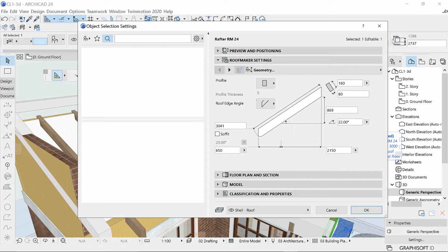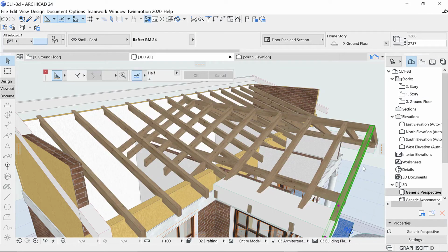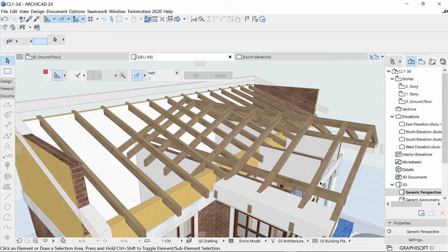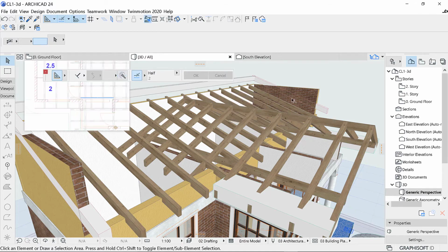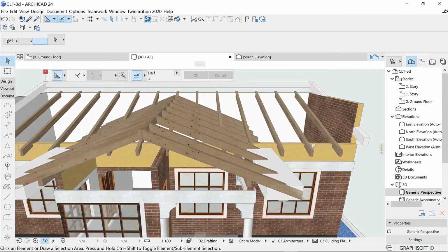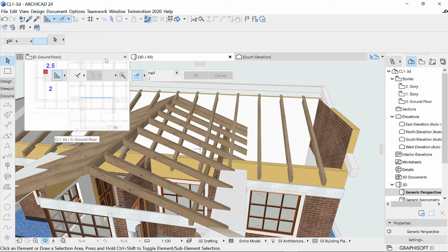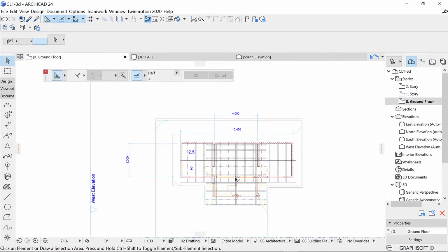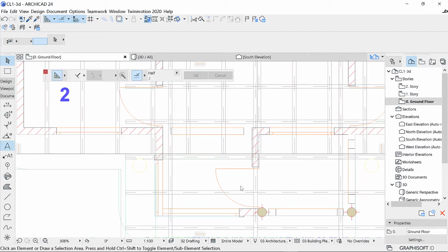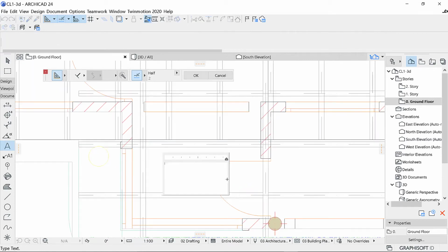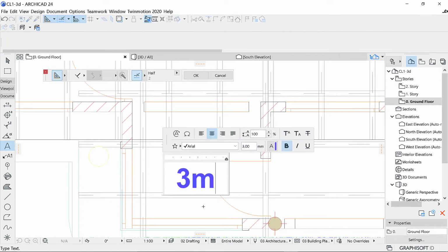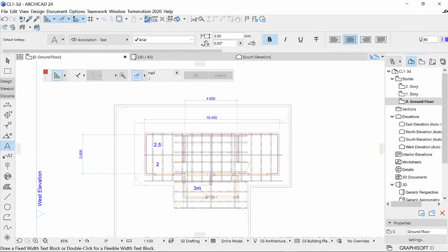So if I'm using 3 meters, the sheet length is 3 meters. It means I'm going to have 5 pieces, because here I will have 1 piece, second one, third one, fourth one, fifth one. This side looks the same as this one. So on this side I'm going to have 5 times 2. This is going to be 3 meters now, that's the type of sheets. I'm going to have this side 5, this side 5. So 5 times 2 gives you 10.